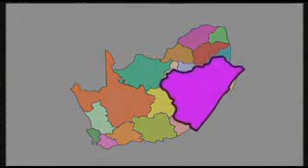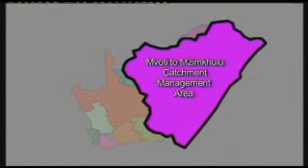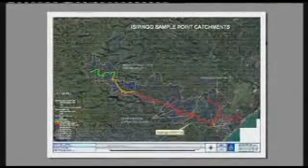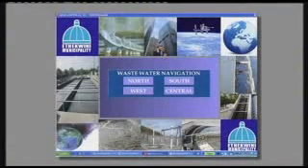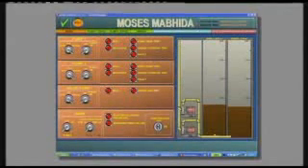When we broke down the catchments into minor catchments, we were able to narrow our focus down to the specific sample points that are giving us problems. And with that, we were able to identify, one, pump stations that were giving us problems, two, wastewater treatment works giving us problems in terms of their discharges not being in spec. And with that came the intervention of installing telemetry on our pump stations, because what's been happening is we were getting overflows on our pump stations and we were only noticing those an hour or two afterwards.